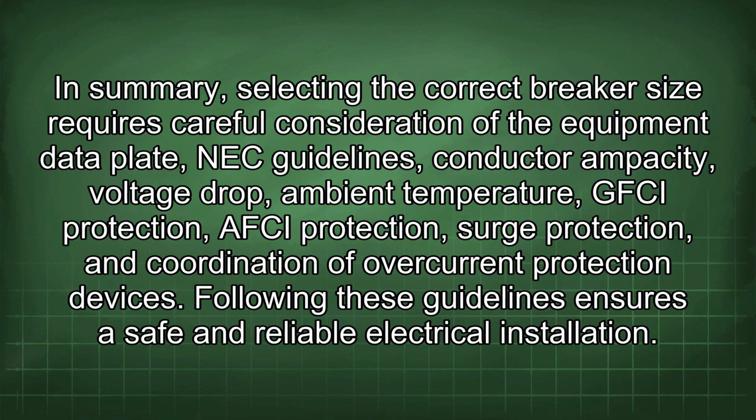In summary, selecting the correct breaker size requires careful consideration of the equipment data plate, NEC guidelines, conductor ampacity, voltage drop, ambient temperature, GFCI protection, AFCI protection, surge protection, and coordination of overcurrent protection devices. Following these guidelines ensures a safe and reliable electrical installation.